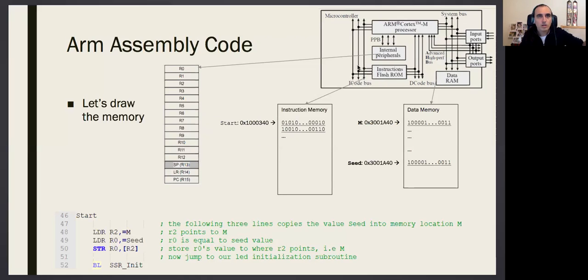Or, the third possibility, I could read it from the data memory here. Well, you should think: reading from a register and reading from the memory, what is the difference? I mean, this is a 32-bit cell, and this is a 32-bit cell. I understand architecturally it is here and it is here, so what is the difference? Architecturally they are different, and in assembly we'll have to do them in different ways. How come? I'll get there.